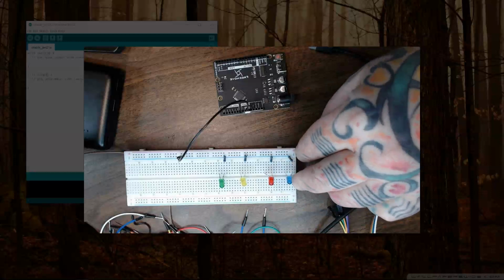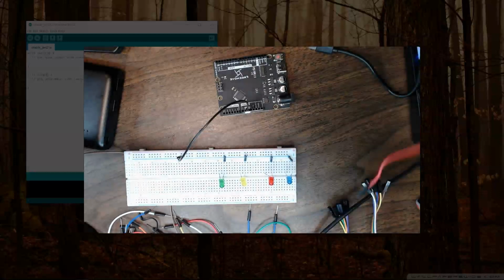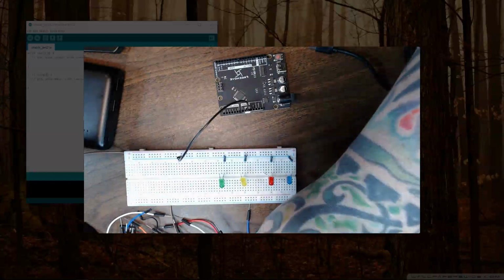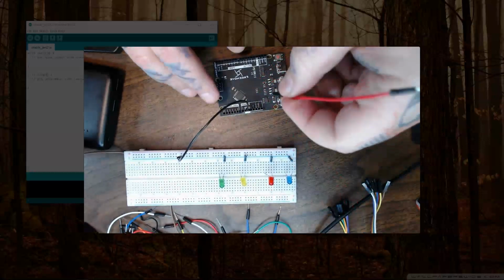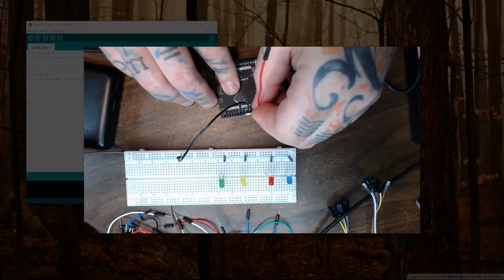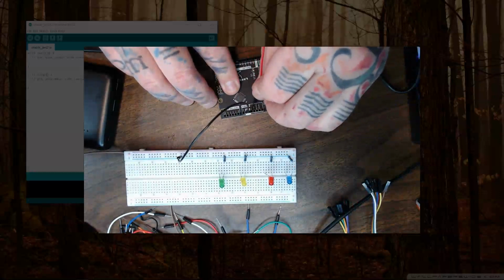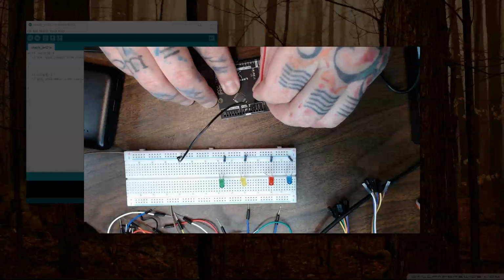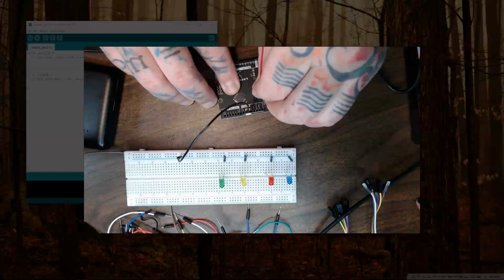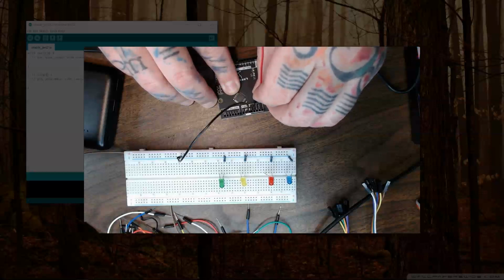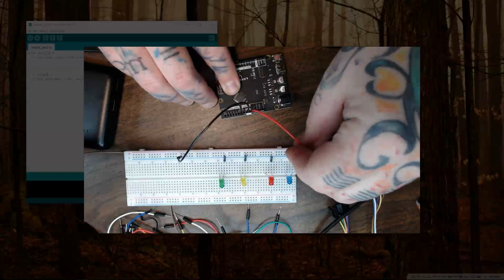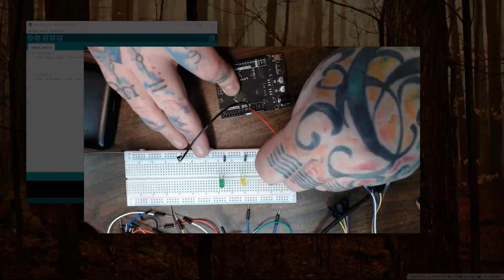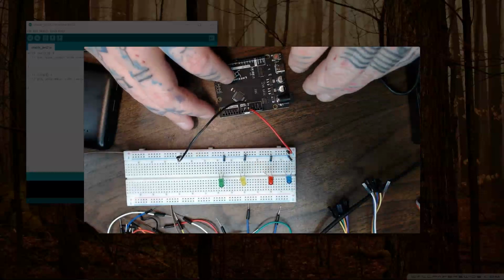We're just going to complete the one circuit on this other side. So now for power, you want to get another jumper cable, and I'm keeping the convention of black for negative and red for power. So, we're putting it into the 5 volt. Just like in the simulator video, where we had the power, I just have 5 volt right here, plugging that in, and I'm going to put it on the actual power rail for now because we're going to be sharing that power throughout.